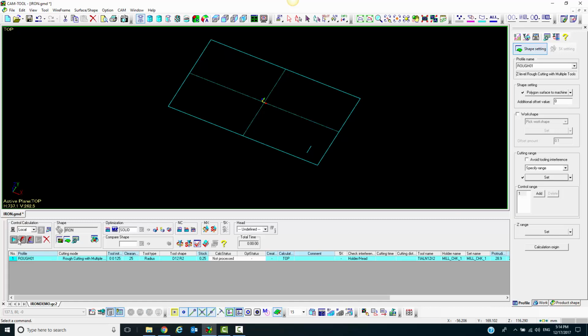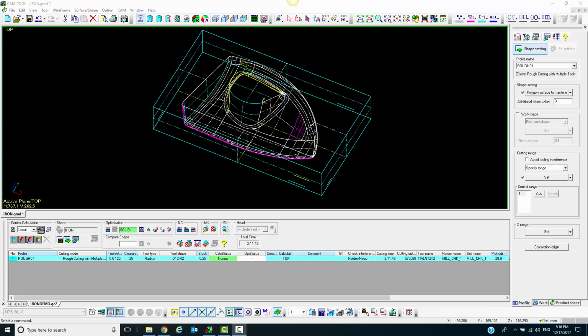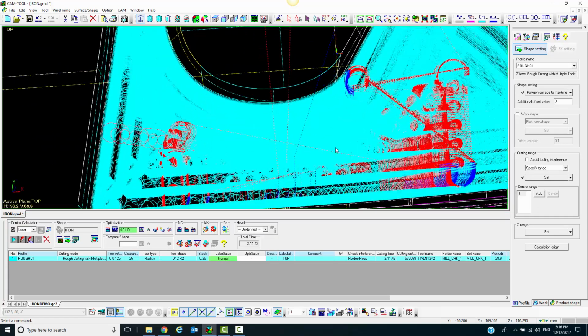Next, we will start the calculation of this toolpath by hitting Start Processing. You will notice that first, the stock model is converting. When it turns blue, it is in the process of converting into a usable stock model. Once it turns green, it has now been converted into the stock model we are going to start our project with. Now that our toolpath has finished calculating, we can double click on the toolpath to see what the toolpath looks like.